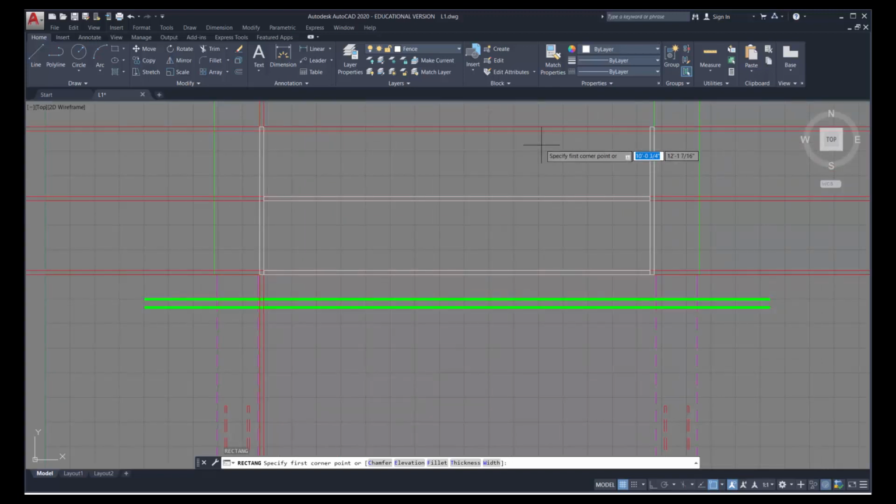Typically with an arc I need a radius. I don't have one here, but I have some other information that's crucial to me. I'm going to click on the lower of these two lines and delete it. I'm going to use the upper line and offset it 5 inches to represent the arc depth. So I'm going to select offset 5 and enter,